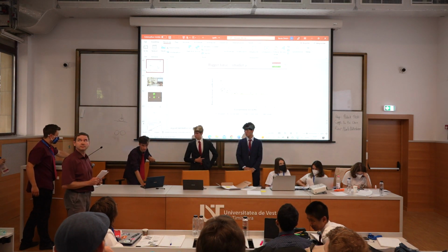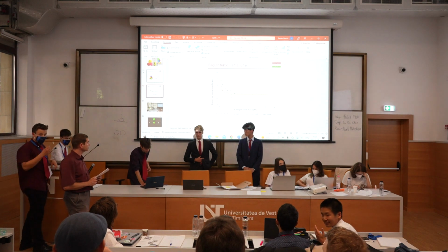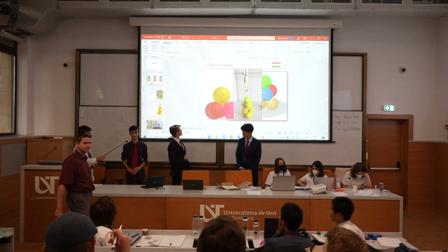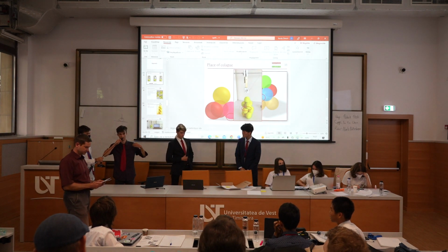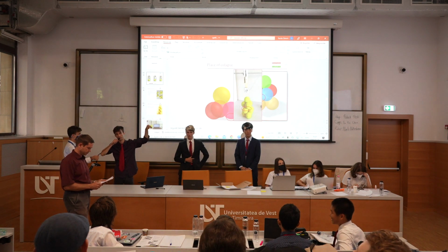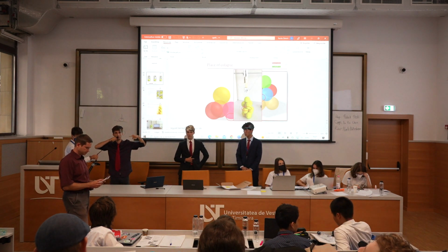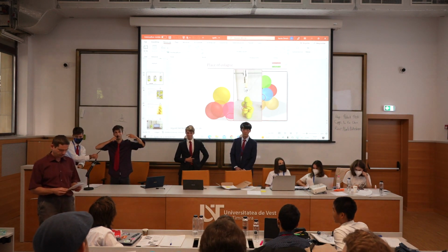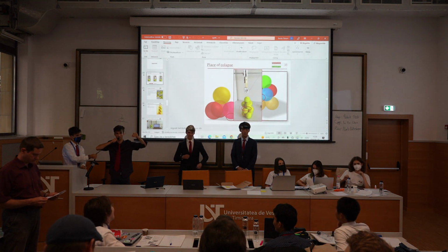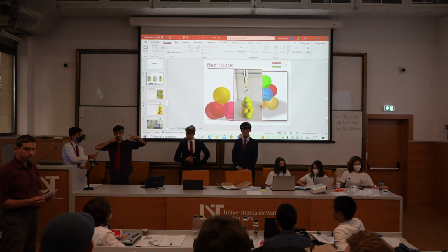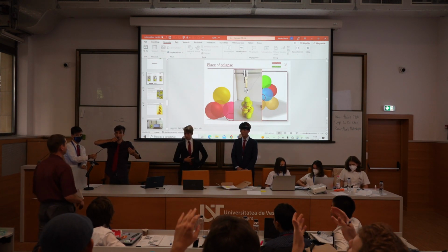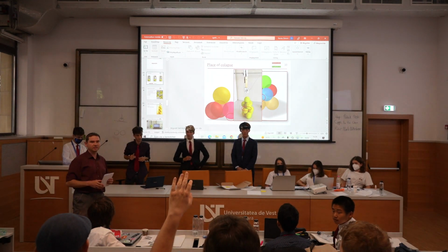At most forces the frictional coefficients were lower because higher forces were acting, but at other parts, for example when the top wall was pushed, we had to calculate with the highest friction we measured, because the compressive forces there were really small. Thank you.